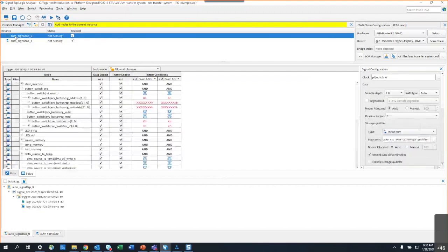Okay, so the next question, I might need this person to chime in a little bit to explain it, but it says, in fact, wiring a signal to Signal Tap may prevent the synthesizer from throwing away that signal, which could be the default state for that signal. Oh, okay, so I think this is about trying to preserve signals. Yes, Signal Tap will keep the trimming from happening.